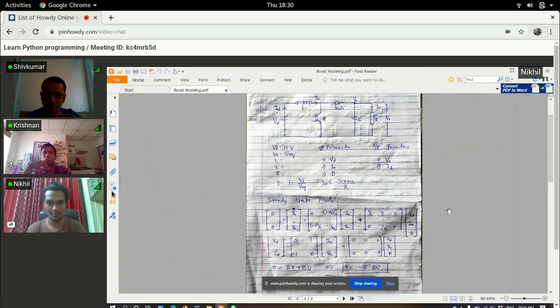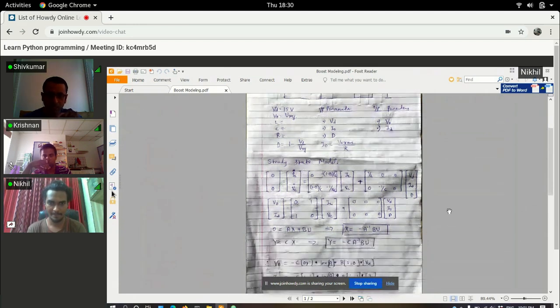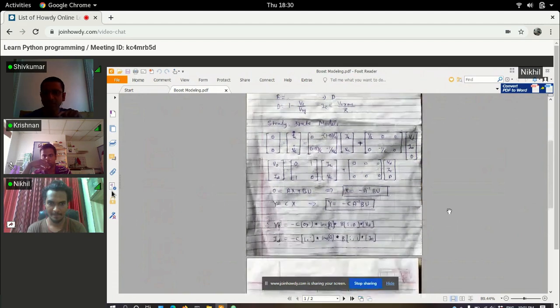The only thing is that the variable ID is not an actual state variable, but is a variable that you are computing from something else. Now, from a control perspective, you may use it to regulate the current that is supplied by the source. For example, in power supplies, not only do you want to control the output, but you also want to make sure that you don't burn the input, because the input should not overheat.